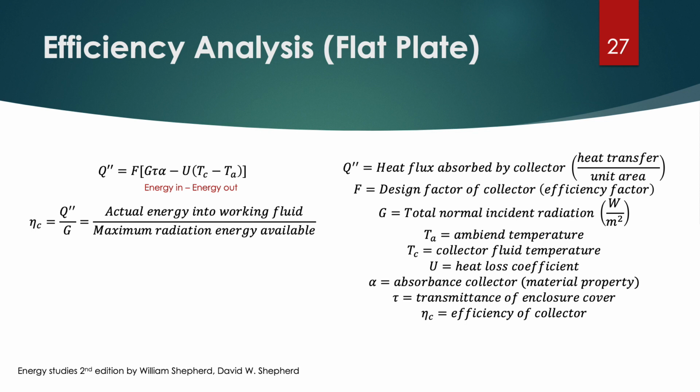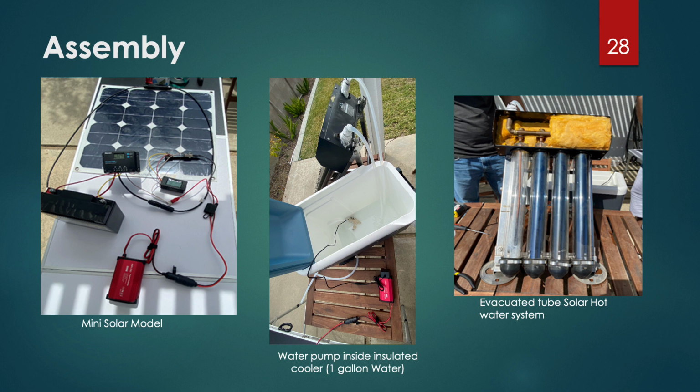Similarly, the solar collector efficiency for a flat plate would be expressed as heat flux absorbed by the collector, also known as the actual energy into working fluid, divided by the maximum radiation energy available. Moving on to the assembly, we have our 12-volt water pump powered by our mini solar model on the left, which is hooked up to our evacuated tube hot water system ready for testing.